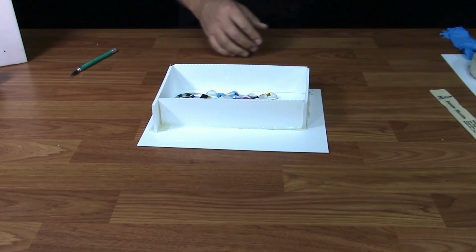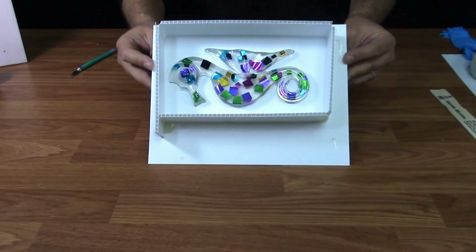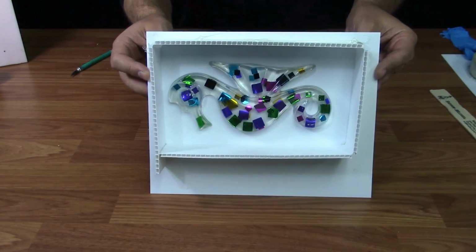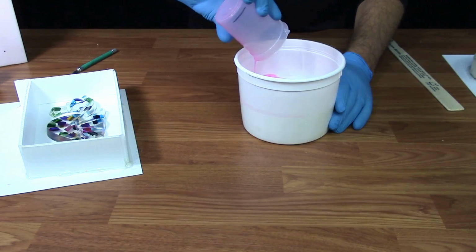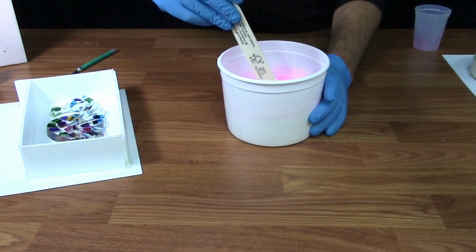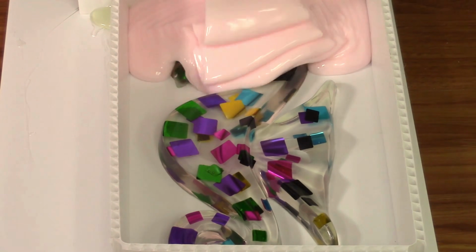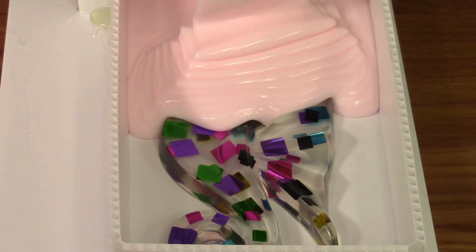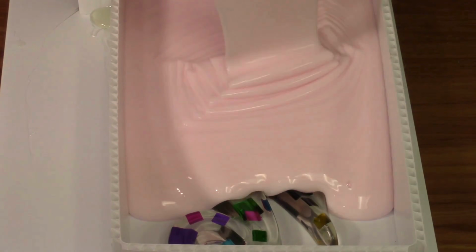Following surface preparation and application of release agents, the master is enclosed within a mold box. Liquid silicone is mixed with the curing agent under controlled stoichiometric conditions and degassed under vacuum to eliminate entrapped air. The silicone is then poured over the master and cured at room temperature or elevated temperature depending on formulation.